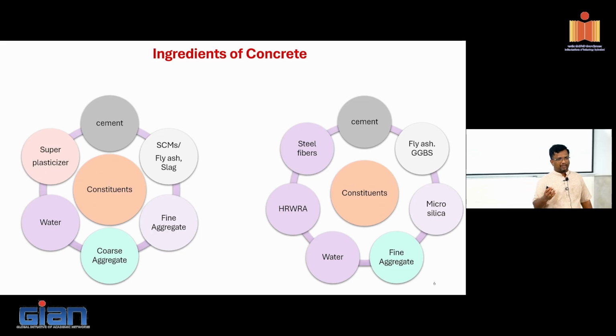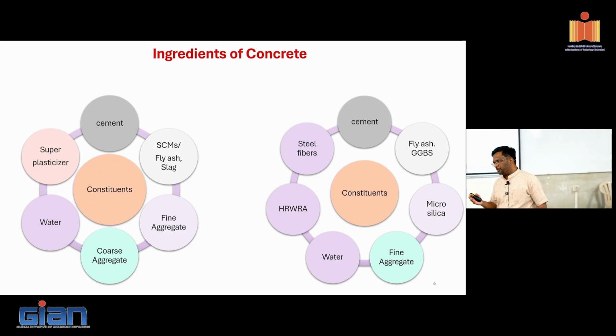Okay. Can I not go lesser? Why can I not go lesser water cement ratio or water to binder ratio? Because it needs reaction, sir. In reaction, for cement, we need at least a minimum amount of water. What should be the minimum? 0.3, sir. I think so. For each species, 0.3. Actually, you don't need more than 0.2.